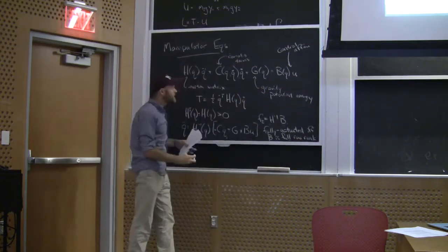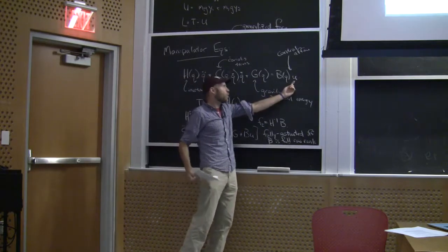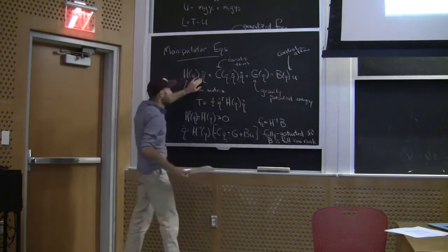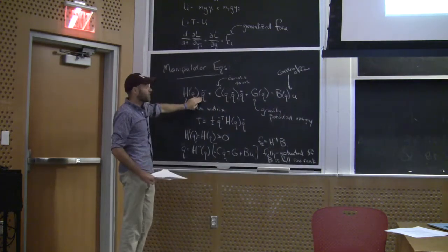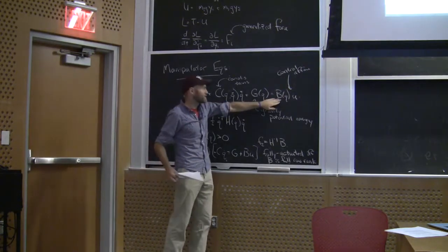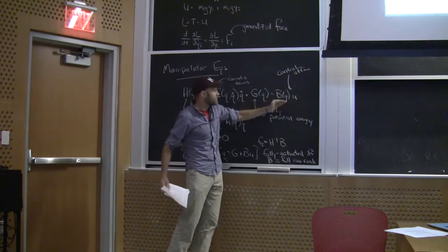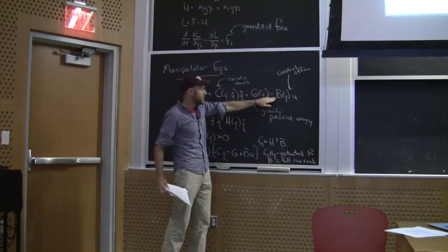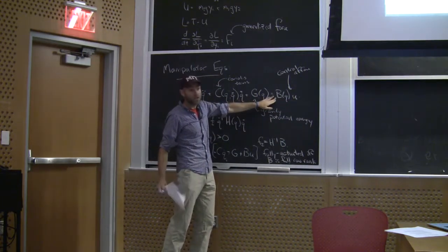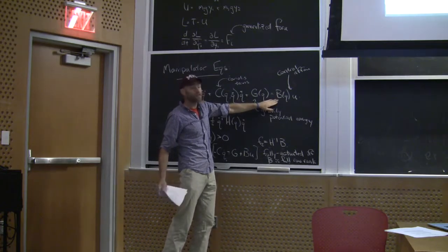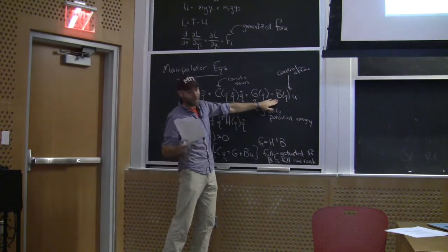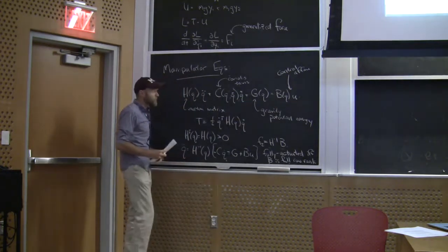Okay? B is this term that maps my torques to my joint space. This is maybe my gearboxes or something like this. This is my map from torques to joint coordinates. If B is full row rank, then I've got a fully actuated system. It's easy to control. If B lacks rank, then I've got a harder problem. Potentially a good problem, but a harder problem.